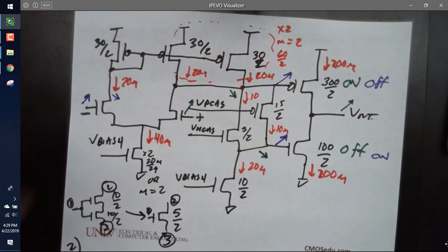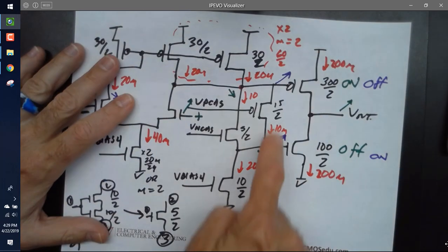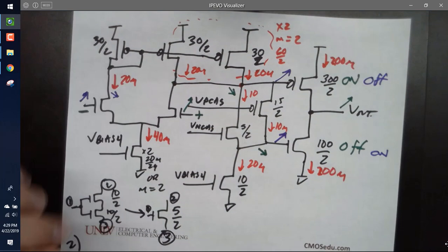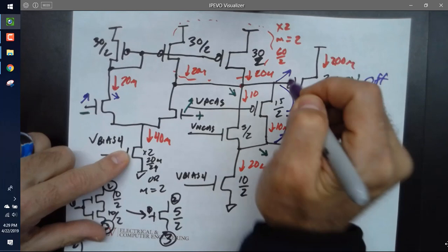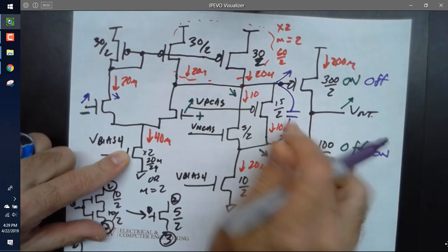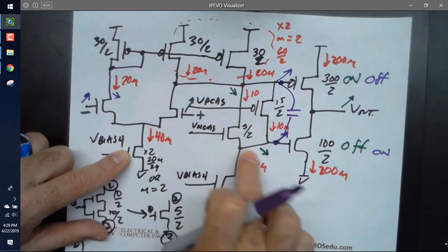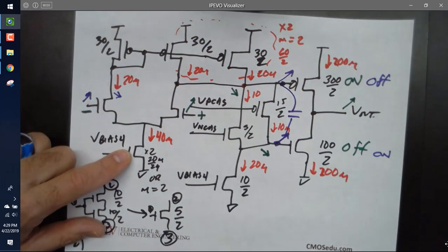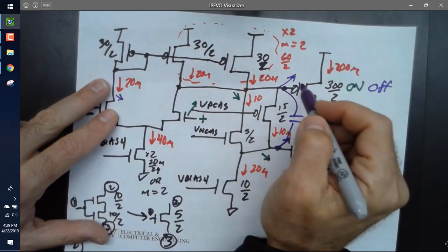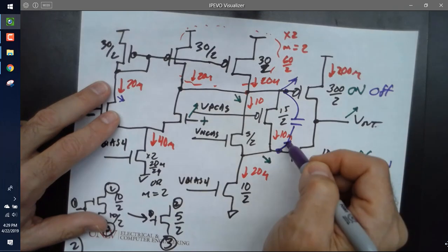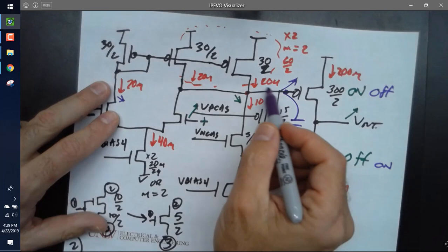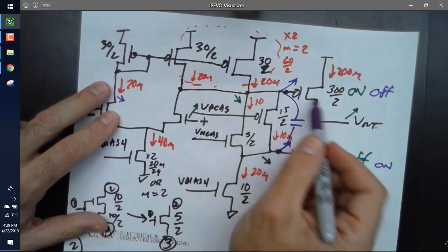However, I want you to notice how I'm assuming these go up together. What you can do in real life is put a capacitance in between those two, and this acts like a battery, acts to keep the currents going. So if this side goes up or down, it feeds and helps the other side go up or down in easier fashion. And so you don't have to spend extra charge charging and discharging the input capacitance here.